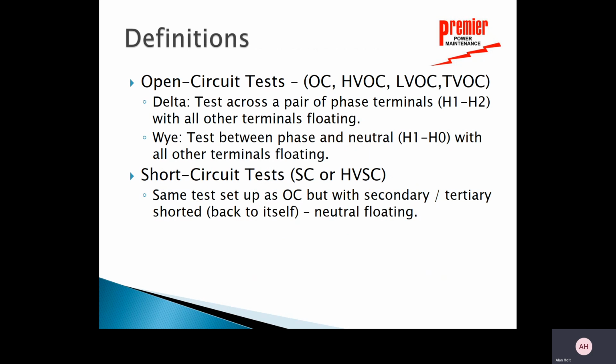So again, with definitions, open circuit tests are going to be called, from now on in the industry, just OC. And it's going to be HVOC, LVOC or TVOC, which is high voltage winding open circuit, low voltage winding open circuit, tertiary winding open circuit.